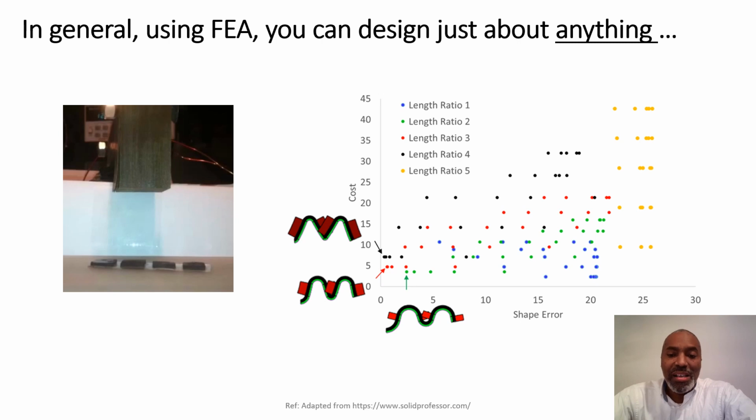This would have been impossible to do experimentally. Those small magnetic patches are made with something called barium hexaferrite, which is really, really expensive. It's about $1,000 a kilogram. That underlying substrate for the silicone elastomer, not really expensive, but it's a pain to make. It takes about a day or two to cure, and so this would be a long time and financially expensive endeavor. But here with simulations, we can knock all these out in about a week.